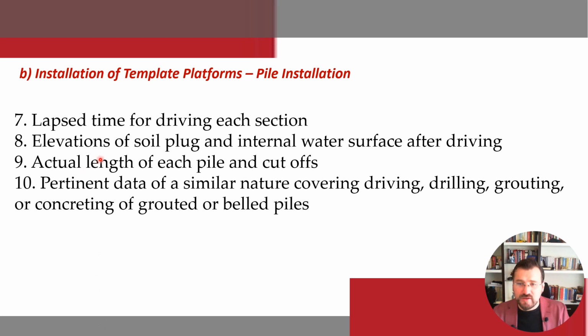Lapse time for driving each section. Elevations of soil plug and internal water surface after driving. Actual length of each pile and cutoffs. Pertinent data of similar nature covering driving, drilling, grouting, and concreting of the grouted or belt pile section. Okay, so